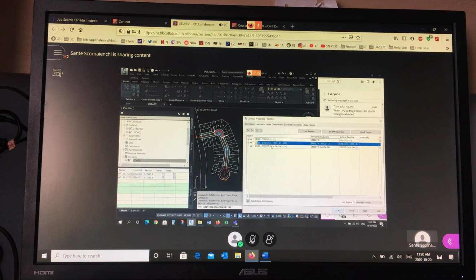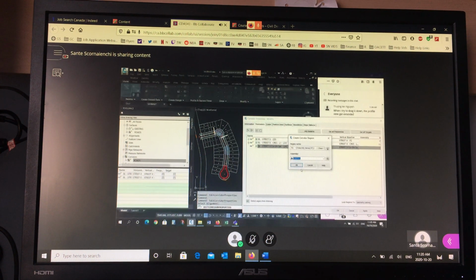To add the region, you right click and you say Add Region. And that's where you add the cross section. What you want is the crescent with the boulevard on the left side. I'm going to reuse that one because I strategically chose 0 on this side to go around this way. Say OK. Let me build what I've done so far so you can see what you have to fix. You don't have to stop and start the way I am. I just want you to see the effect of the different functions. So I'm just going to add those 3 pieces and let it go.